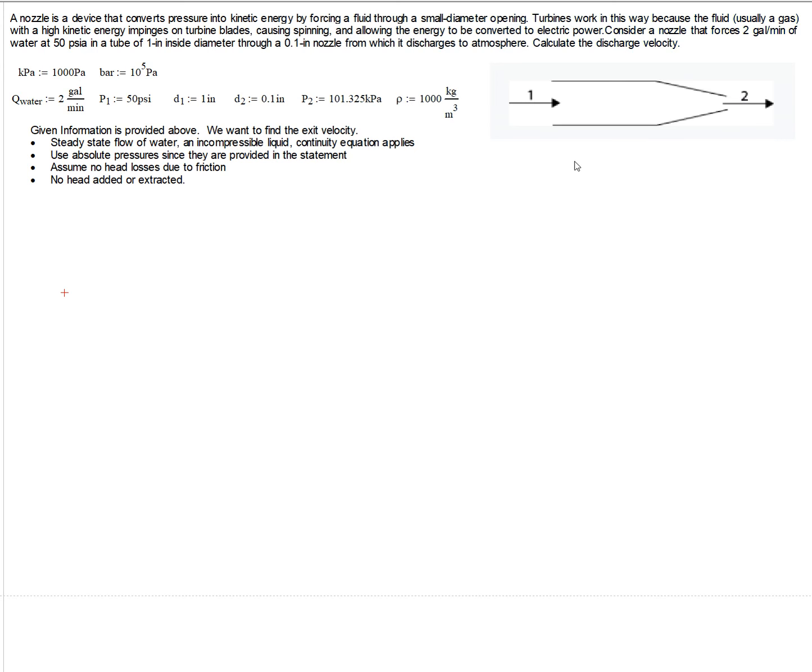One of the common mistakes that I've seen among students before they really start thinking about process fluidics and how fluids flow is they always think that higher velocity must mean higher pressure. For example, when you take a garden hose and you restrict the flow with a nozzle, the water comes out faster. And the naive assumption is to think that faster velocity is higher pressure. That's not true. It is at a lower pressure here than what we have here. If it were higher pressure at position 2, then water would flow backwards.